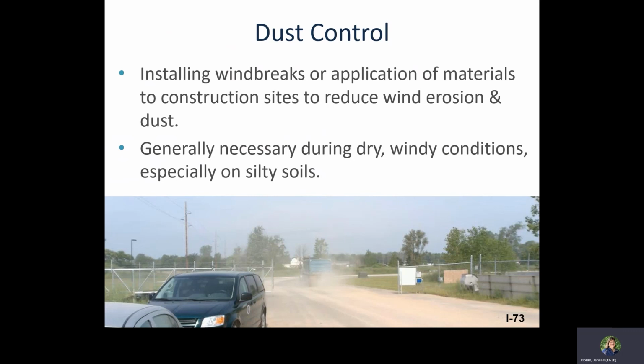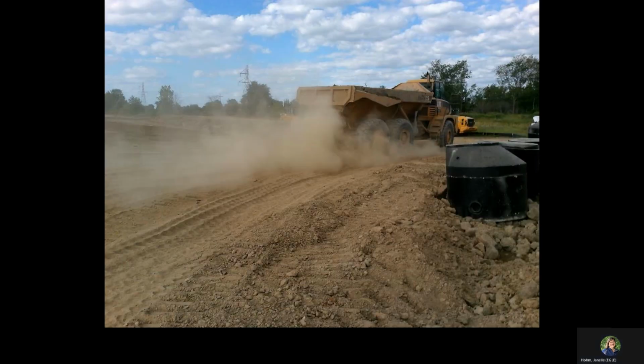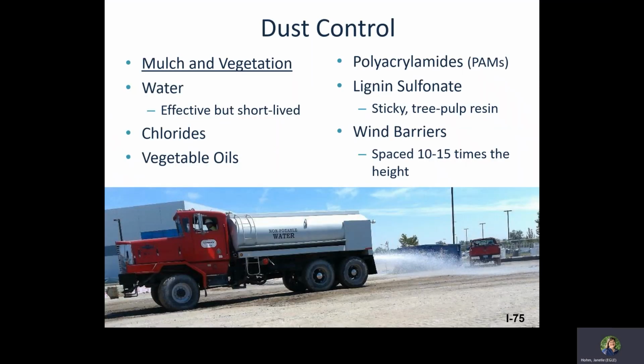Leaving natural windbreaks in place is recommended if possible. Other techniques include the use of snow fence perpendicular to the prevailing wind, the application of PAMs, daily watering, and hydroseeding. On a large, flat, unvegetated site, sediment generated from wind erosion is generally greater than that generated by water erosion. The training manual may be referenced for more information on these dust control methods.